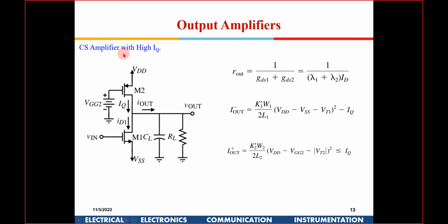Now if you see here, this is one amplifier. What is this? It is a normal common source amplifier, but it is capable of driving low loads. Why? Because the resistance seen into this amplifier is very low. So we said R0 parallel to R01 parallel to R02, but we are ensuring that R01 and R02 are very low. How is this done?